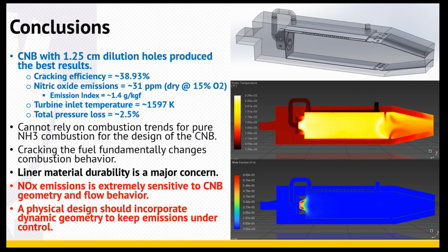You've got to think these holes at most have like a 2.5 millimeter difference between one another, and they produce such wide swinging results. What this means for a combustor is that unless it's locked during operation at one condition for the majority of its runtime, you're going to have a problem with your emissions, because if you change the environment it's operating in, you change the fuel and air flow rates, you're going to get these wide swings in your NOx emissions.